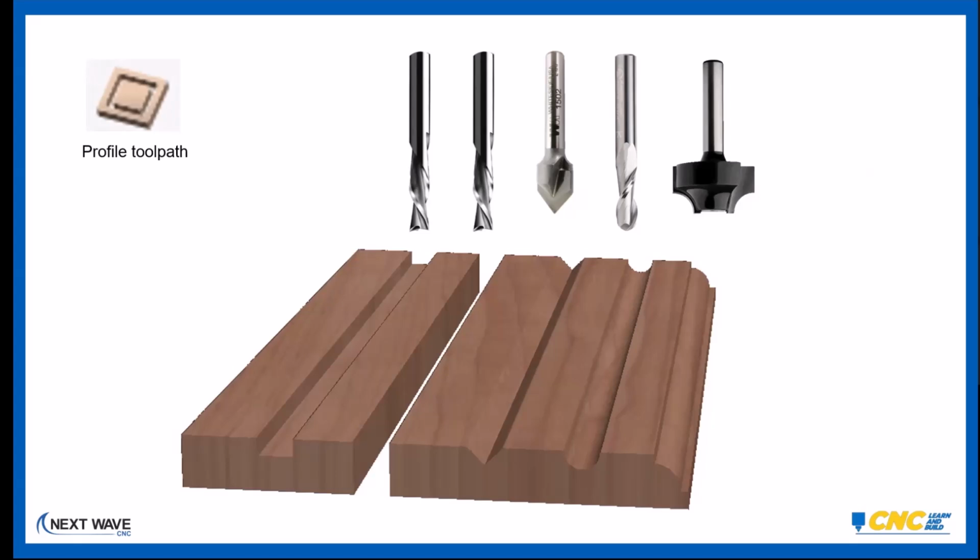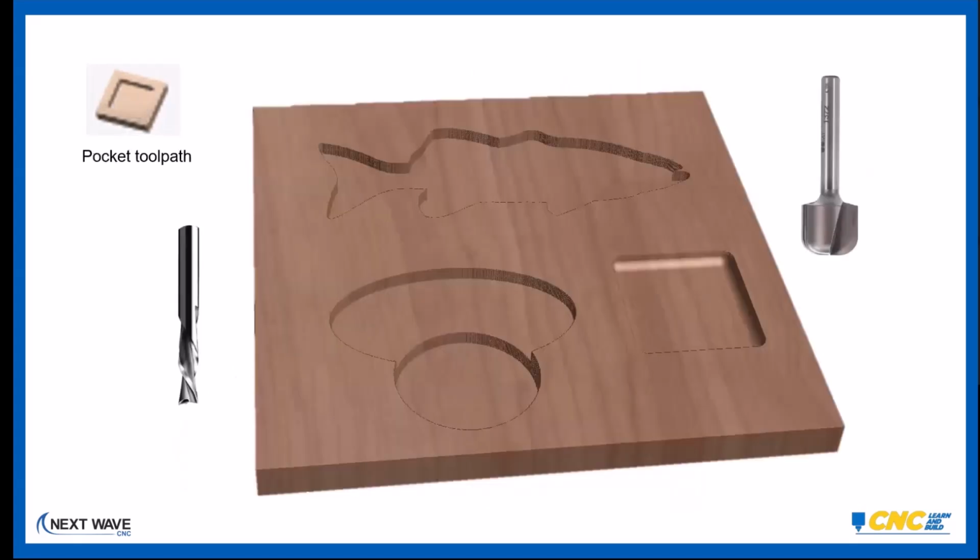The next one is a pocket toolpath, and it's obvious from the pictures here that it's for pocketing out or routing out an area. Again, you can set it for a certain depth, multiple depths. You can go all the way through the work also, though that's not as common.